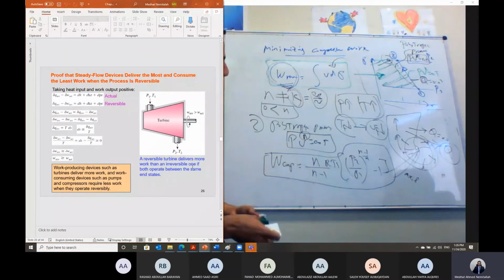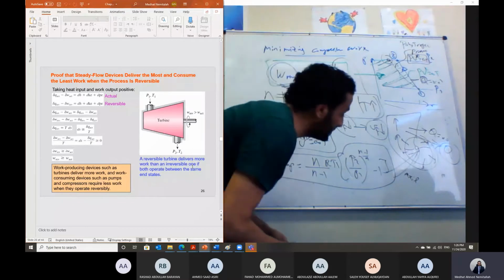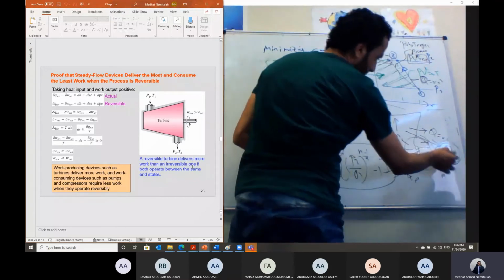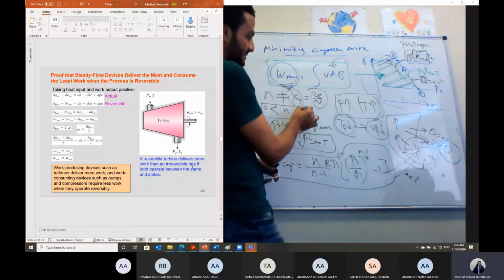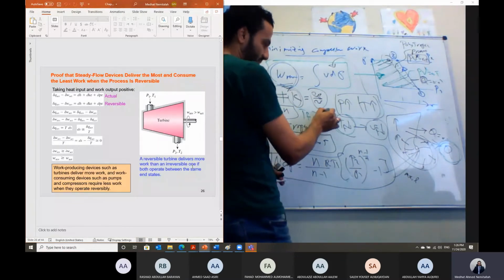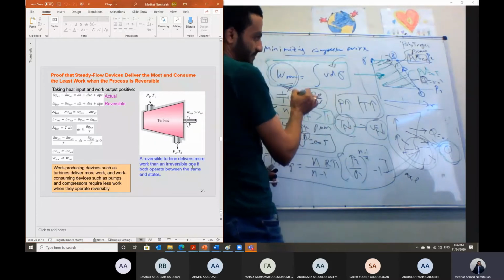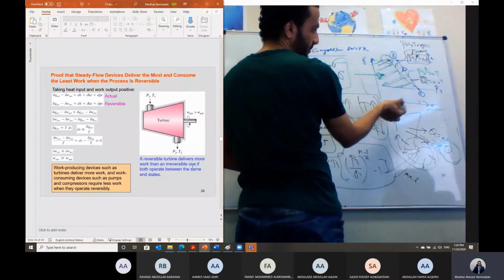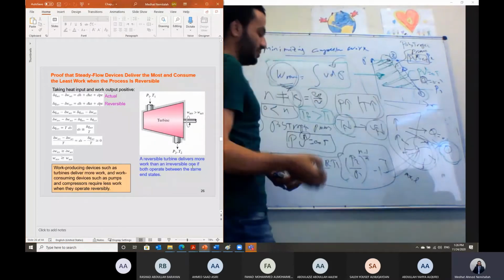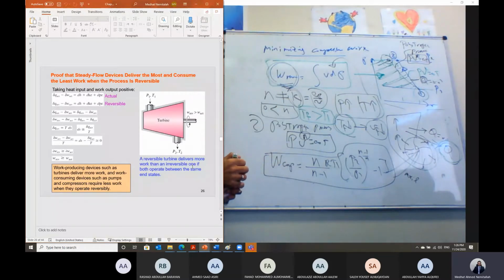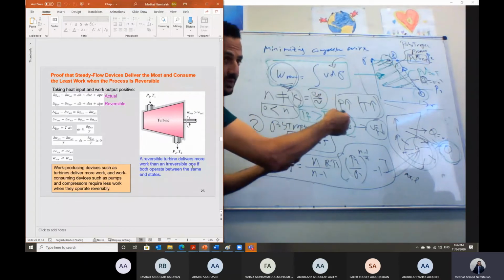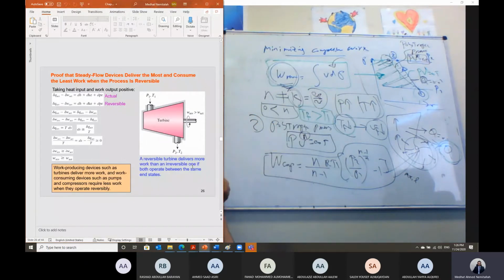So here in this case, guys, we said for the polytropic process, we allow the system to exchange heat. So the final temperature is reduced, but still the final temperature is much greater than the initial temperature. So T final, which is T2, is much greater than the temperature T1. It is increased, but compared to the isentropic, it is less. The final temperature is less than the isentropic.